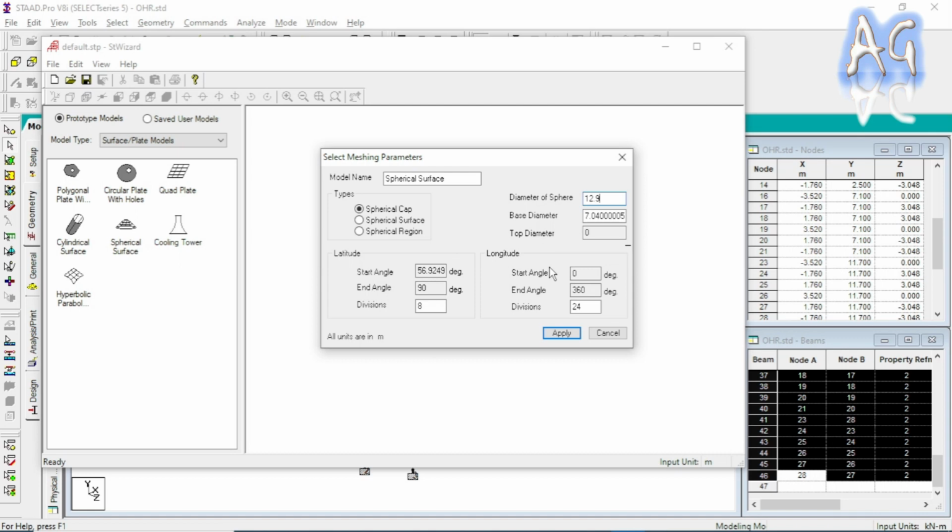So you have to divide the plate member along the longitudinal direction so that the plate node merges with the column node, otherwise the column node will be in between plate nodes, and the load transformation will not happen. So you should provide a division which is a multiple of the column number.